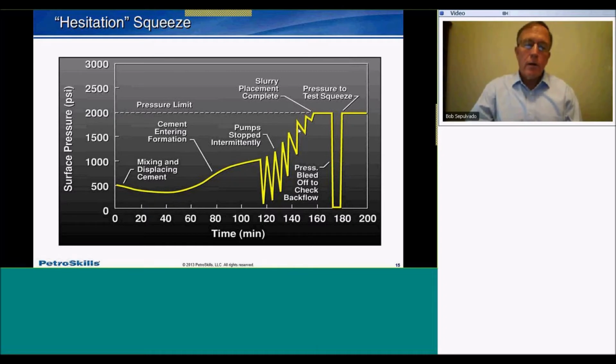If somebody has experienced squeeze cementing in an area, they can provide guidance on adequate distance to place the packer above the perforations. The other thing from an operational standpoint is when we do this, we do not want to exceed the thickening time, the working time of the cement slurry, because at the end of the operation, we're going to have to reverse excess cement out of the tubing if not all of it is below the packer.